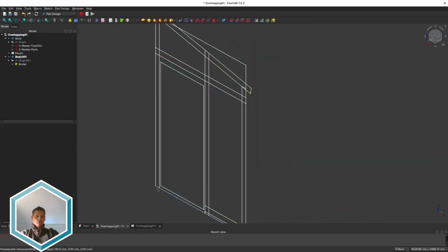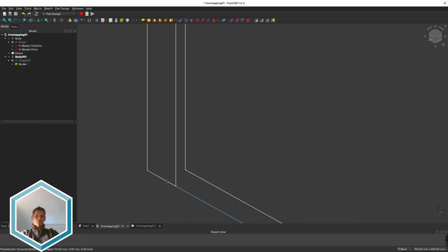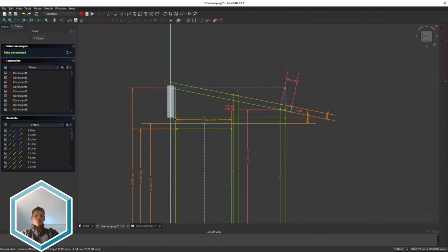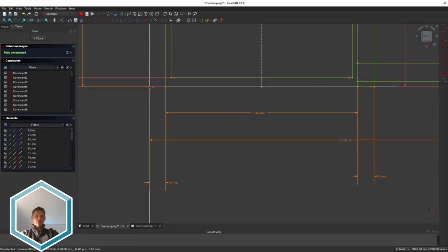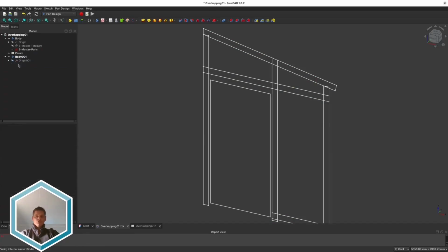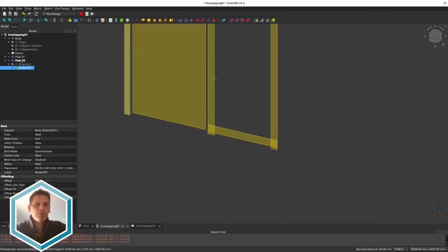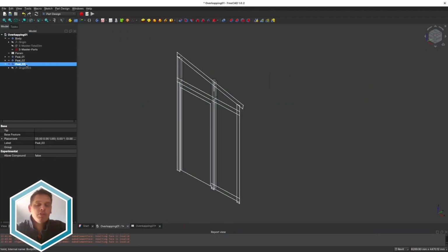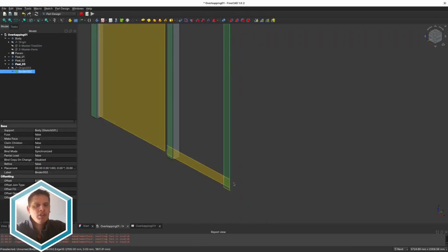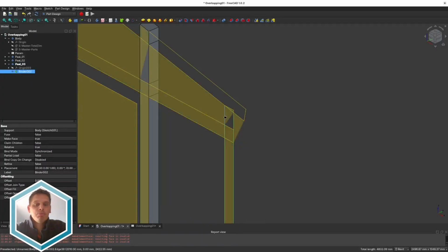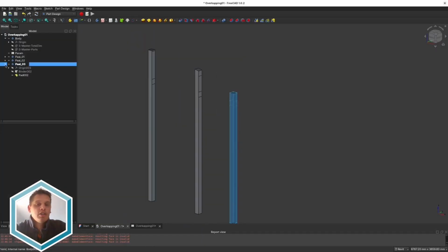Alright, so the normal square that you see, or rectangle, I mean, is the overall dimension, and the little green one in front of it is the main master sketch for all the different elements. What we're going to do is make a lot of different bodies, and every body will have a shape binder to this master sketch, and from the shape binder we select the parts that we need, we extrude them or pad them as FreeCAD calls it, and then we do some array or cloning and make an overhang.